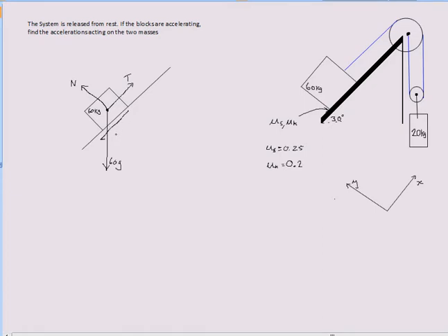So let's first consider the case that the sum of all external forces acting on it are trying to move it up the hill, which implies that the friction force will be down the hill to try and resist movement. If we're trying to figure out whether this block is going to be stationary, we need to concern ourselves with the friction force mu S n. I did a video describing roughly how to use mu S n. This is just going to be a particular example of using it in a more sophisticated example.